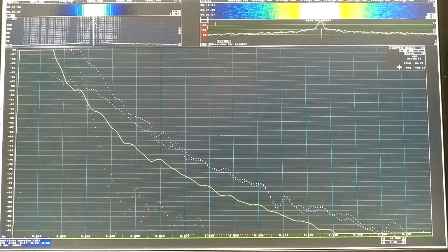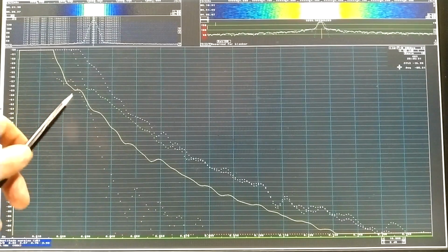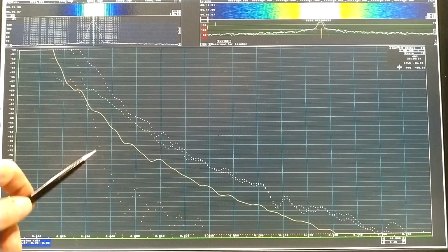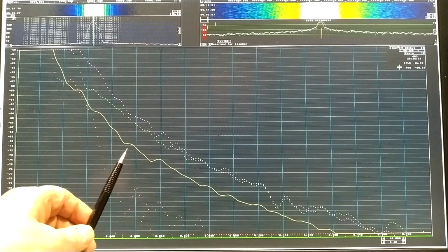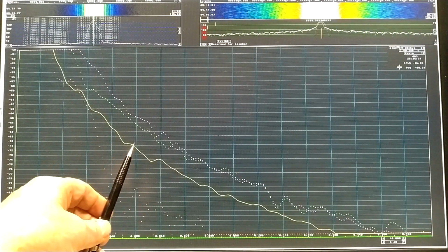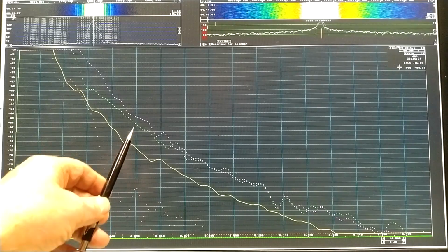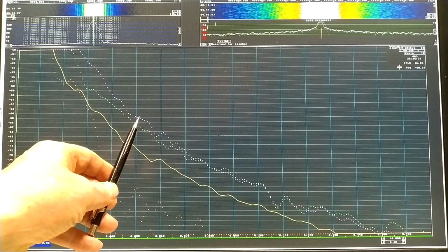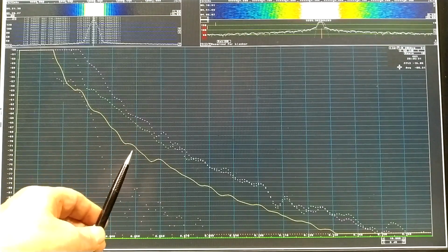In the linear frequency scale, here with 1 decibel per division, I can read values from 0.02 Hertz, and here maybe there is a problem because the imaginary part is so strong. So I don't know what it means, but I can see at 0.05 Hertz that this oscillator, the one I'm testing, is significantly better than my reference oscillators because the separation is more than 3 decibels.